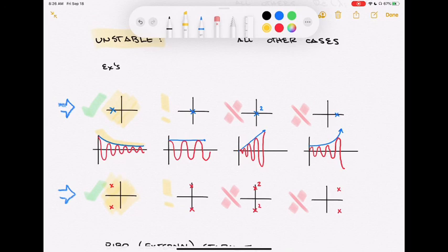Like this next one, I took that single real root and moved it over until it was right on the omega axis. It turns out this is the origin. This is a root, lambda equaling 0. e to the 0t is just a constant, right? And that's why that blue line, corresponding to that blue root, the mode, is just a constant. This is that boundary of stability.